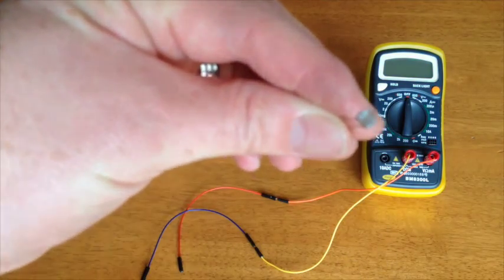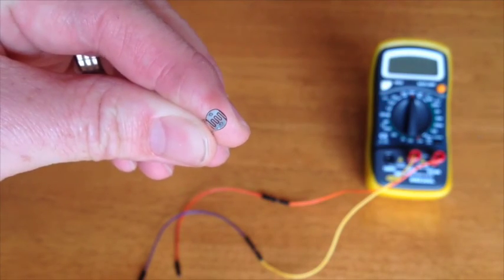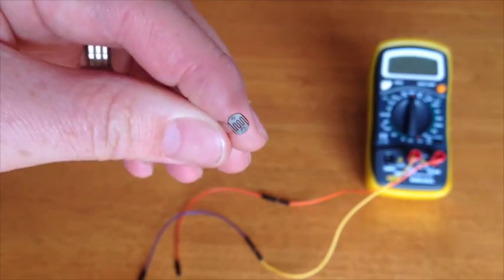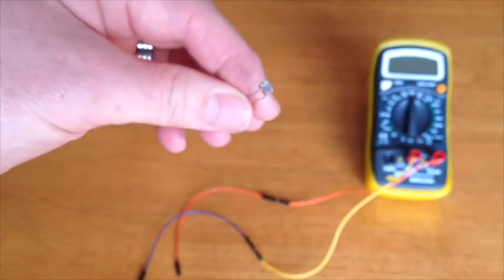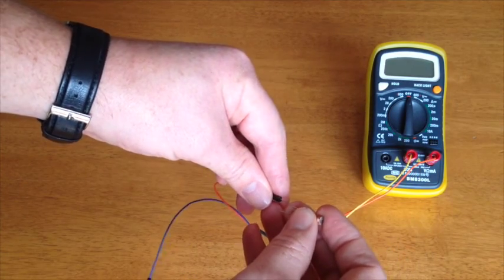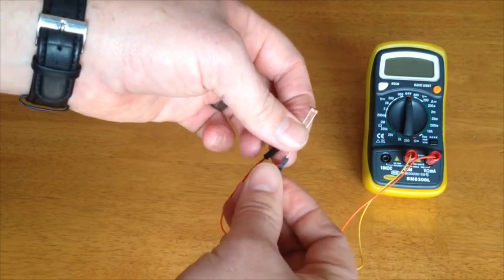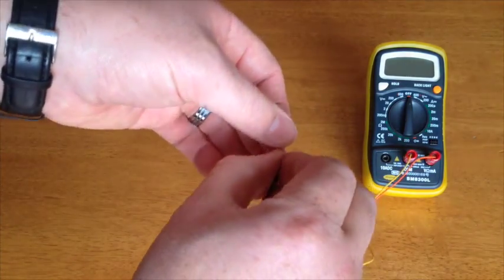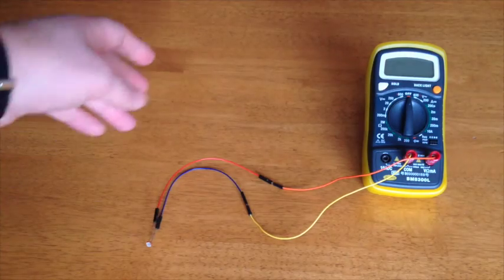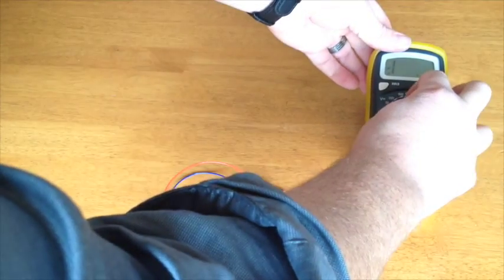Okay, so here is the LDR itself. And as you can see, that's just a very small component. And this measures the resistance due to the light intensity. So what we're going to do is take this LDR and plug it into our multimeter. Then we're going to switch to measure the resistance since it's a light dependent resistor. So now that means that you've got one possible dependent variable being resistance. You could also set the LDR up in a circuit and measure voltage or current through it.